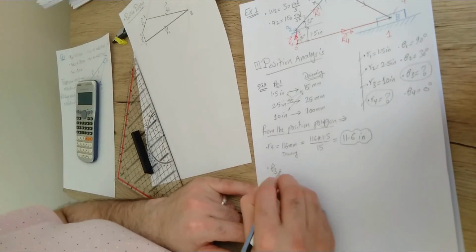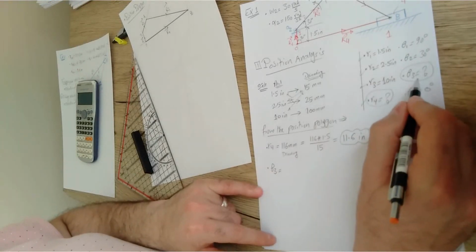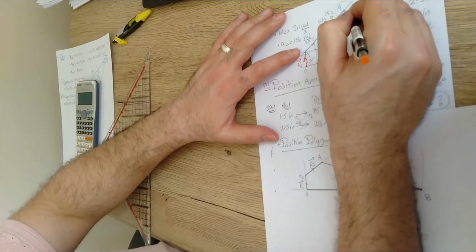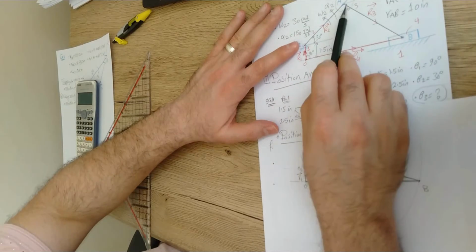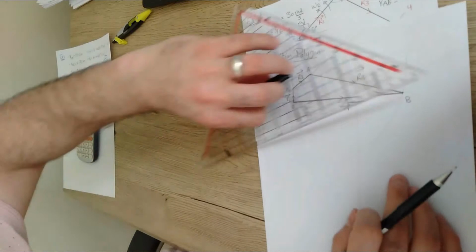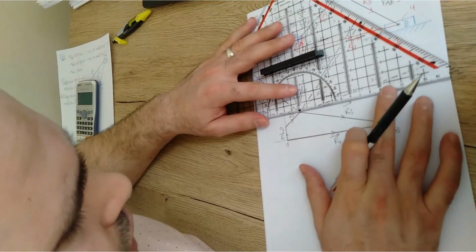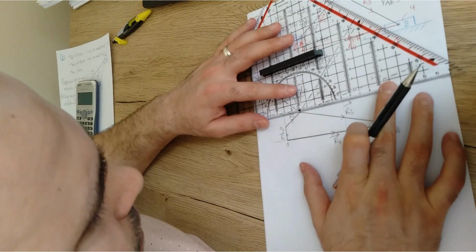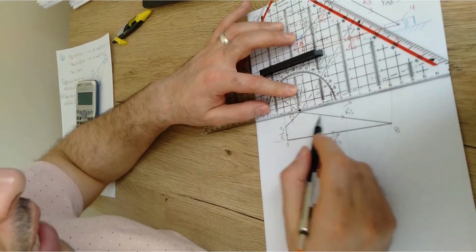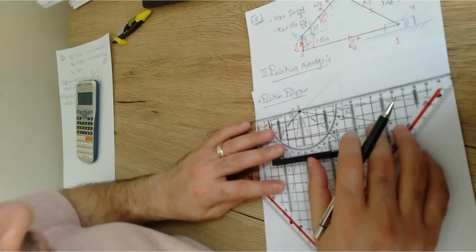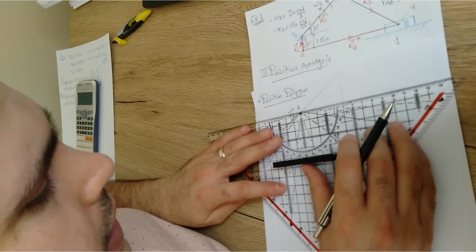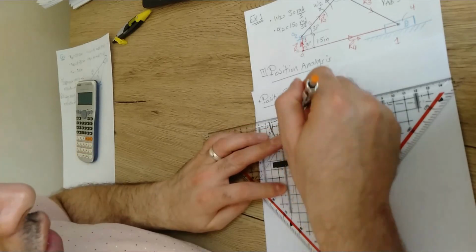Then we have to measure the angle, and remember there is no scale for the angle theta 3. As we defined here, theta 3 is just the angle, and we can simply measure this angle between the horizontal line and the inclined line. From this point A, I'm just gonna fix here, try to align one of these lines to be parallel to the vertical line, to make sure that this edge is completely horizontal. No, sorry, my bad, I should measure in this way. It should be aligned here, and make sure that this edge is completely horizontal.